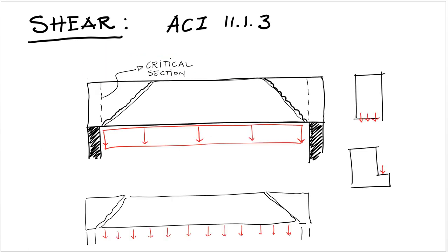Another exception occurs when the beam is loaded at the bottom, right? So if you have a load acting at the bottom of the beam, such as in the case of a beam that has a ledge and carries a load near the bottom of the member, when we draw the failed structural member right here and we draw the cracks, we see that the free body diagram of that member after it fails includes all of the load along the member.